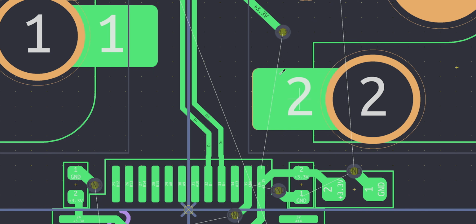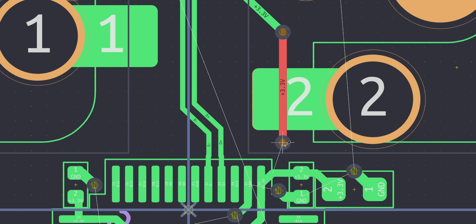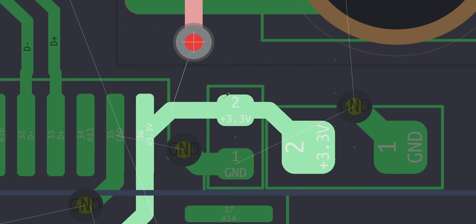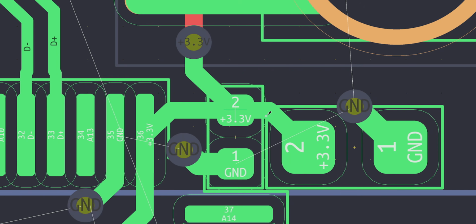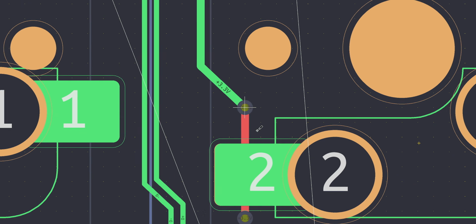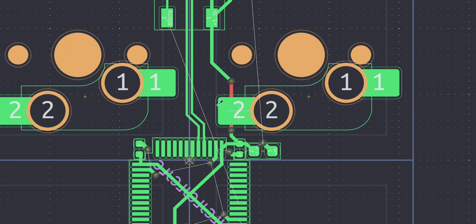I'm going to put a via, then pull it on the other layer to jump over the hot swap socket. Then finally, it doesn't really matter where you put it here. I like to route it into the capacitor here, and that feeds the rest of it with voltage. So that's the rough idea of how I route my voltage, as far away as possible from any data stuff. The only thing you're really jumping over here is the hot swap socket.